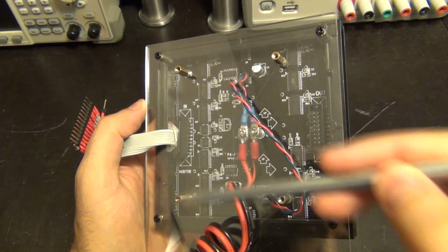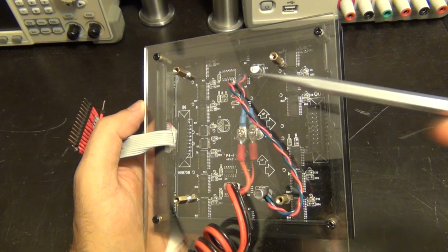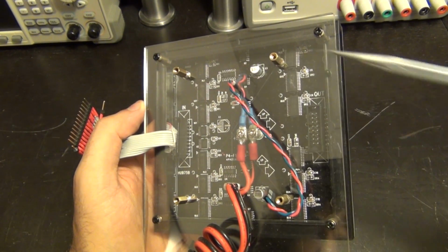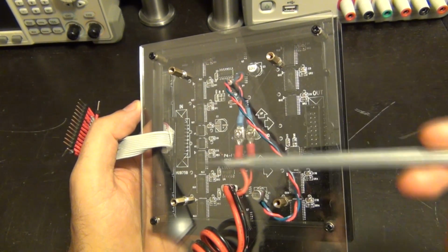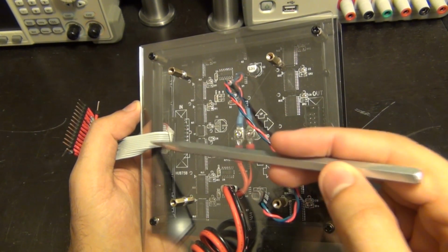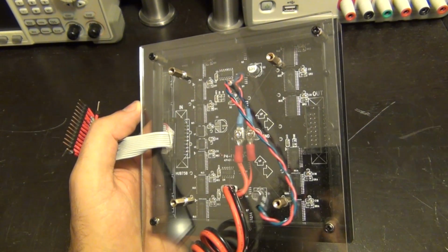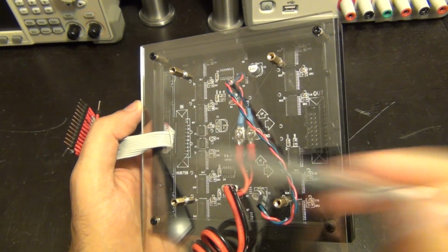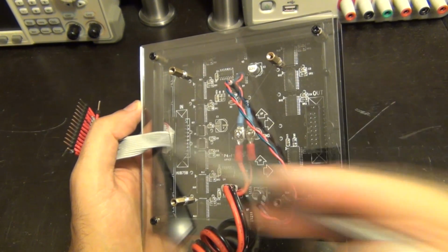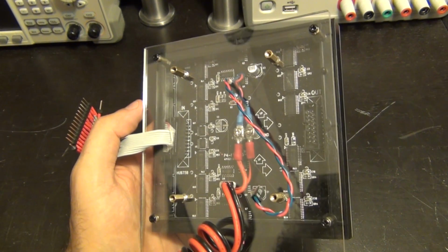Now the construction of the RGB LED matrix is really simple. It has row drivers that drive each individual row depending on which row is selected by a 4-bit address. And all of those are basically these ribbon cable interface here. You can see there is an in and an out. That's because these are supposed to be cascadable so that you can program multiple of them in a row from only one interface. This is very common for RGB LED matrices, that they all do this.